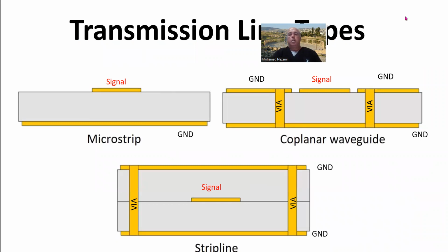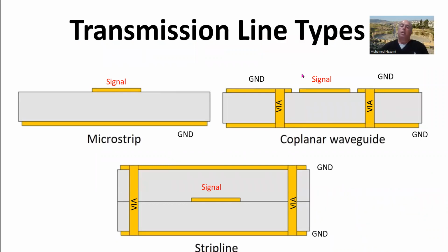Okay, so let's see, how do you go about designing one of these in the board? When you have a board that you're designing, say for a SATCOM transceiver, a receiver or transmitter, at the beginning you choose your stack layer, and you finalize that. Then at the beginning you have to establish these things, and you come up with a map for the vias into the stack layer.